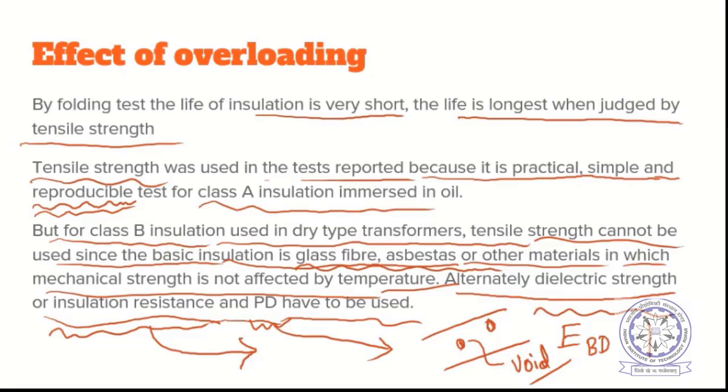For example, on a sinusoidal curve of input voltage, at several points there may be some discharges like this. These discharges occurring within the voids are known as partial discharges. We will cover partial discharges in much more detail in the next semester. For the time being, this much information is enough for you. Measuring the charge in these discharges will also indicate the current status of the insulation material.